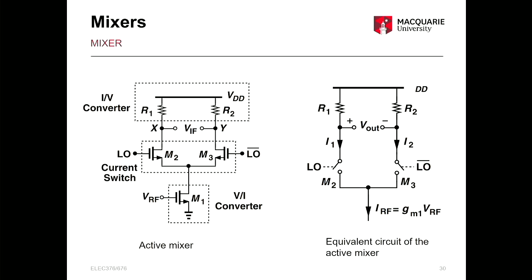So in that case, the previous circuit, where we were superpositioning VRF and VLO, how does that work? Because that's an OR gate. Yeah, so there you were adding two signals and giving them into a square law device where you are squaring it.